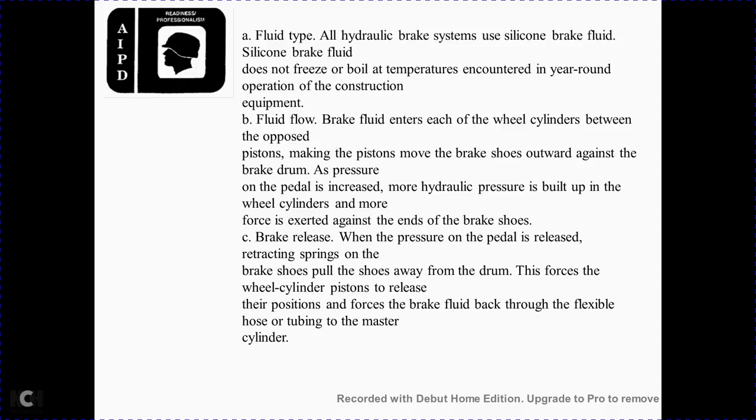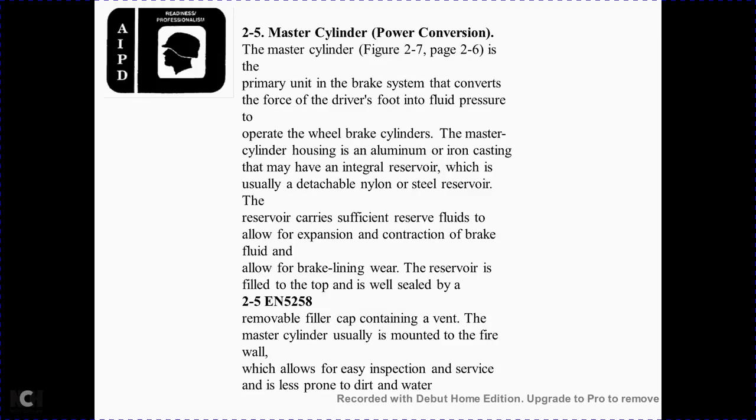As the pressure on the pedal increases, the more hydraulic pressure builds up at the wheels, and the more force is exerted against the end of the brake shoe. Brake release: when the pedal pressure is released, the retraction spring of the brake shoe pulls the shoes away from the drum. The force of the wheel cylinder pistons sends the brake fluid back through the flexible hose and tubing to the master cylinder.